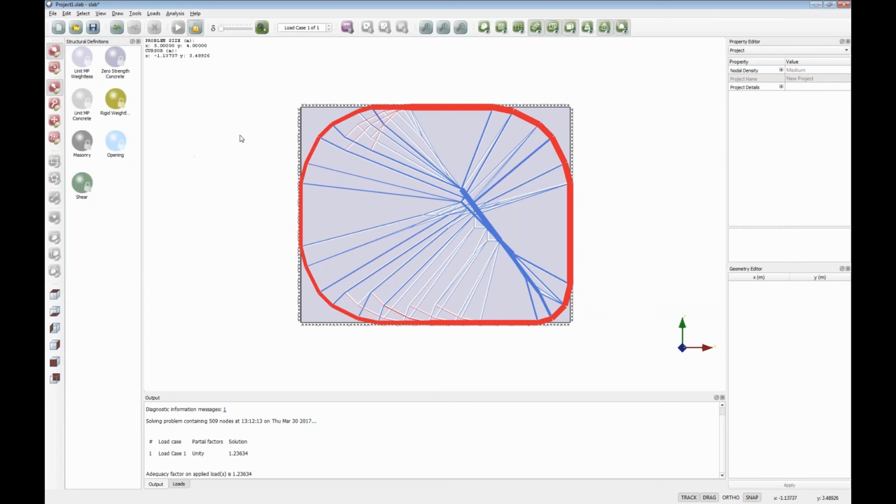So you can apply line loading like that, you can apply point loading in a very similar manner, and also if you want to, I've probably not got enough time here to explain it, but in some of our other webinar recordings which are on YouTube, we can take loading and move it across a slab in order to simulate the movement of a vehicle, for instance, across a bridge deck.